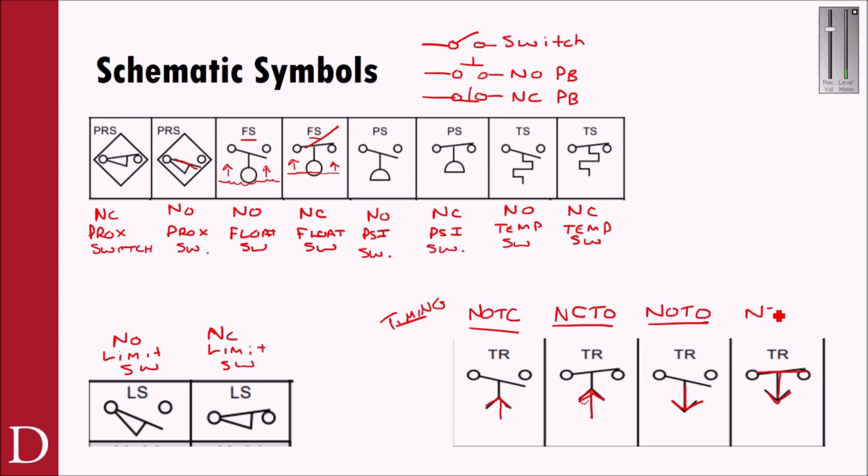It's time to close. So this one here starts off in a normally closed position, energize the coil, it opens up, and it delays to close again. So it's kind of funky symbology there, but the big thing is pay attention to the way it's drawn, normally open, and then pay attention to the action or the arrow.